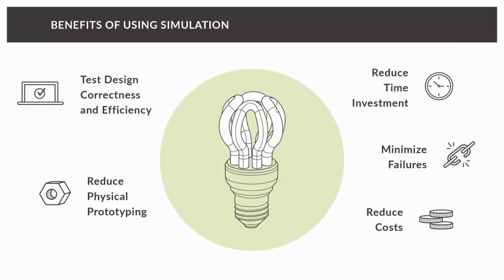What also is a very big advantage of CFD in general is that it provides us with a different kind of results. When we do physical testing, the amount of information we will acquire through this is limited to the number of physical quantities we are able to measure. So if we want to measure the flow field of the HVAC duct, we will only get as much information as pressure probes, for example, we have. CFD, in contrast to that, actually gives us for every point of our domain detailed information about the physics.